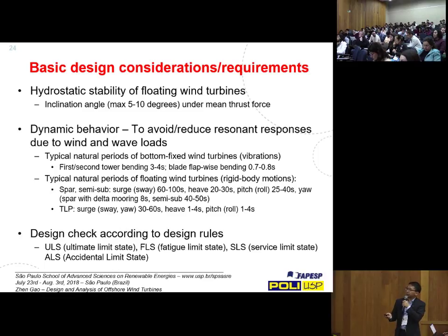And then for the TLP system, we design a quite stiff system in heave, roll, and pitch. And this gives us more or less 1 to 4 seconds, which is also smaller than most of the wave periods.